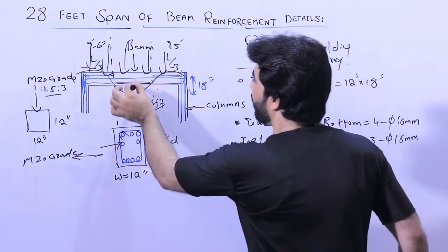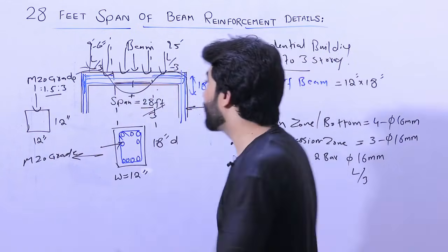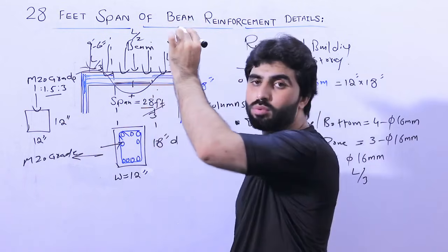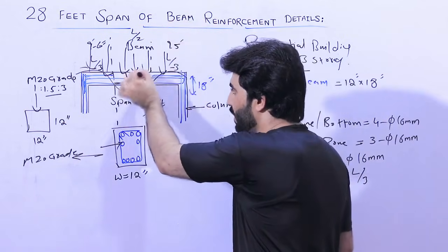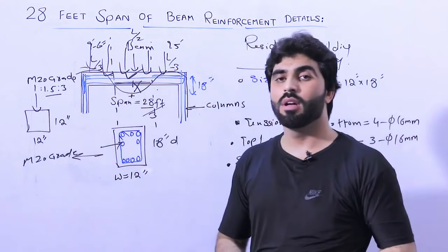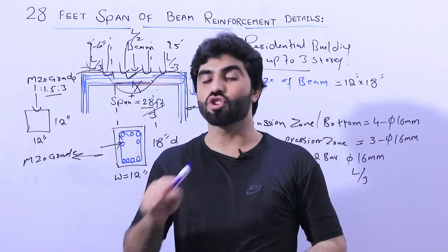So don't provide here at the bottom. If you require to provide the lapping length, provide at the top portion, but at the middle provide lapping at the distance of L/2, not at the bottom, but you can provide at the top. So this is the proper way of steel reinforcement, because concrete is weak in tension, but it's strong in compression.